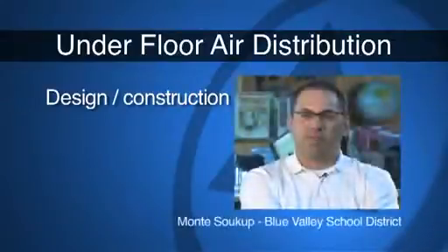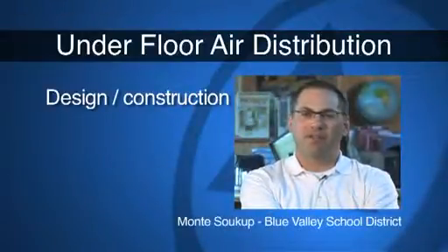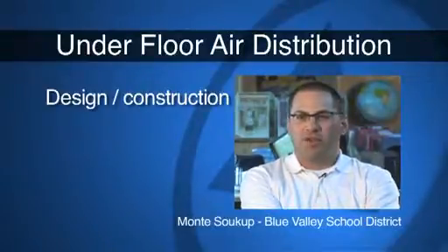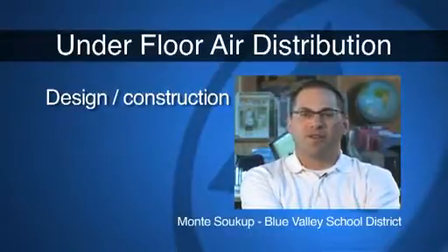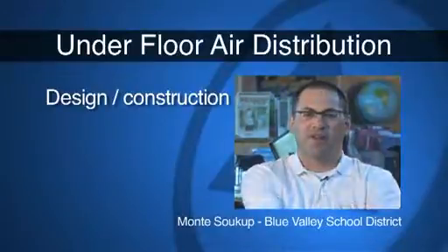It does simplify some things late in the job. The coordination above the ceiling is almost eliminated because you've gotten rid of all this large ductwork that's in the overhead space. So you're not trying to coordinate that with the fire alarm and the sprinklers and the lighting and all that. Underfloor air is no different than any other system when it comes to following proper design and construction guidelines. We just need to be aware that they are different from that of traditional ducted systems.